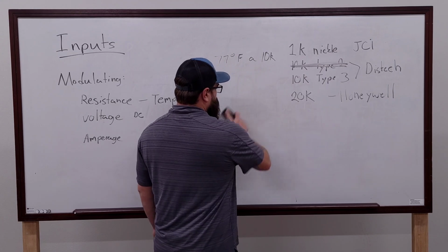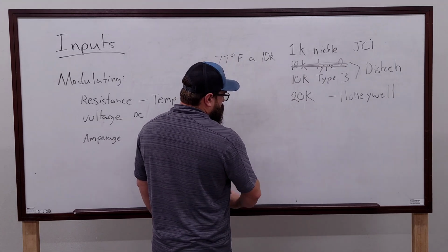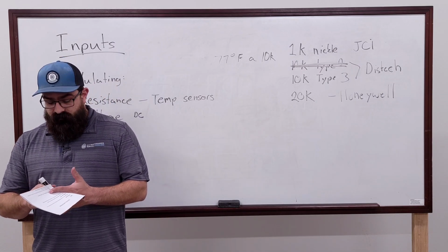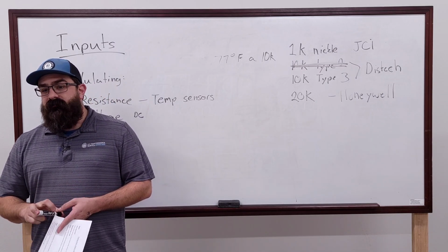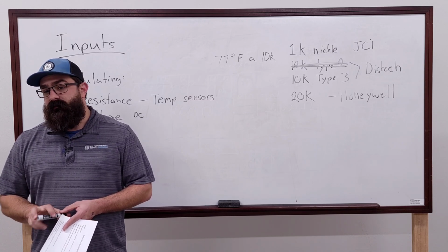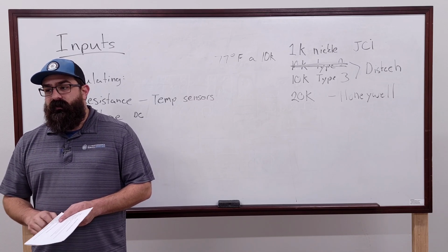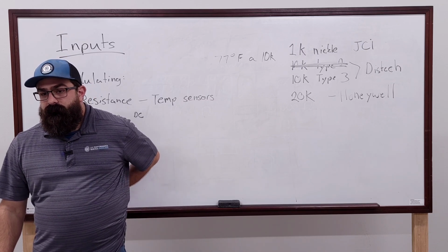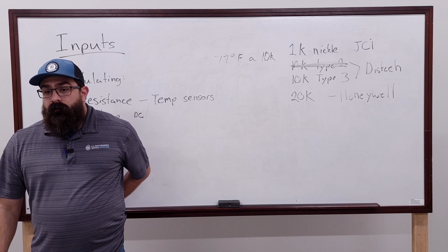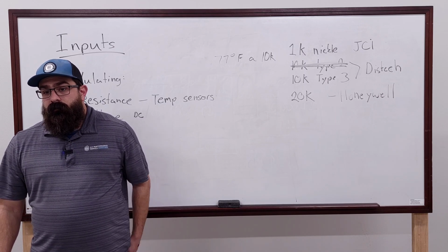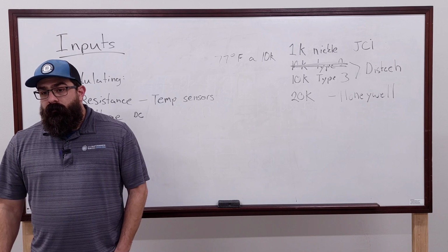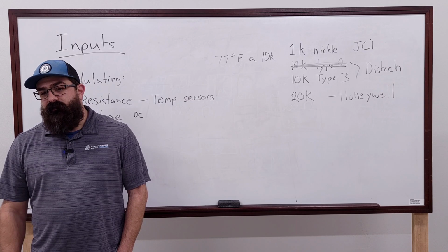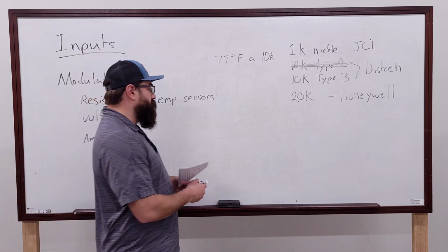What range of tolerance would you give? It depends on the sensor. Each sensor has its own range of tolerance. Most of them are 3%, some are 5%. You would find that out by looking up that part number. As a rule of thumb in service, we use a 2-degree rule of thumb. If we're within 2 degrees, plus or minus.